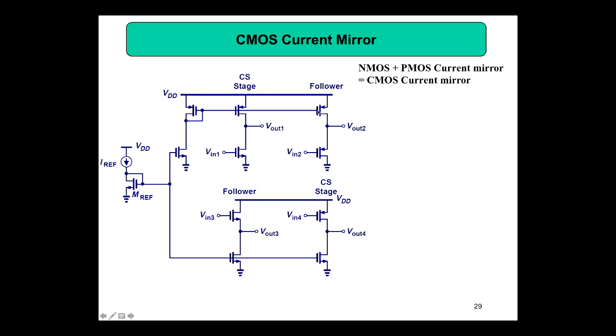But when you have PMOS, then you have a problem. You need an NMOS for biasing. But for NMOS, that is pretty simple. What you do is this stage is common for PMOS circuits and NMOS type circuits. So we will use only this mirror, and this part we will be connecting to your band gap reference, this current. From the band gap reference it is coming, and this will mirror the current, depending upon how much current you need.